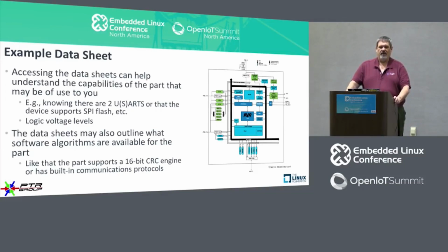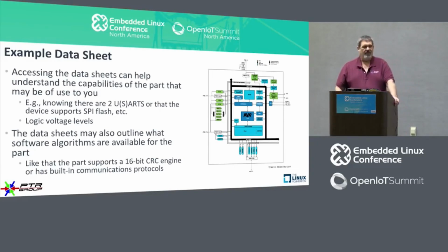Additionally, they may very well talk about SPI flash interfaces and things of that sort to give you an idea of how the board is supposed to boot. And then if it's a SPI flash, we can then hook onto the SPI flash and try to read the flash directly. But more importantly, it gives you some information about voltage levels, logic voltage levels. We don't see much in the way of 5 volt anymore. It's usually 3.3 volt or even all the way down to 1.8 or 1.2 volt logic.